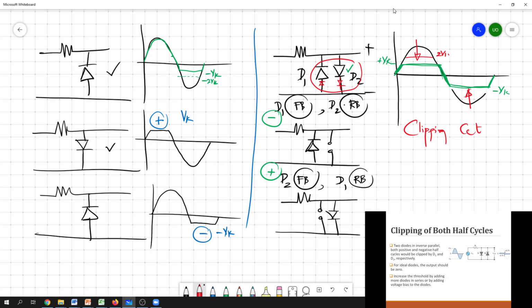When the diode gets forward bias, you can simplify the circuit using an appropriate replacement for the diode. If it is ideal, you can simply replace it with a short circuit element. If it is a simplified model, you can replace the diode with a fixed DC source of value Vk. If it is reverse bias, you can simply replace the diode with an open circuit element, for the ideal model as well as the simplified model.